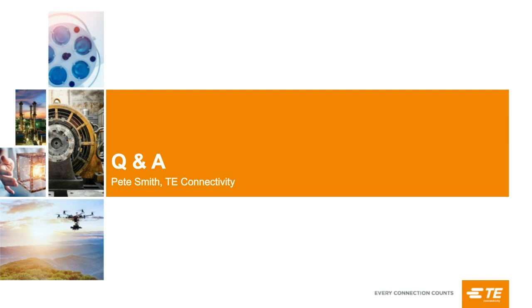When you're harvesting energy from a temperature differential, it's my understanding, and this is not an area of products that we make, but I know a little bit about it, that typically what are used are called Peltier junctions. These Peltier generators are devices where there are 2 plates and you put a different temperature on each plate. In other words, you have a temperature differential across the transducer. And it's my understanding that the amount of energy that you produce is proportional to the temperature difference. In other words, the bigger the difference in the temperatures, the more energy you can get from them.